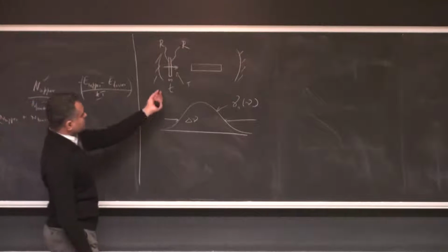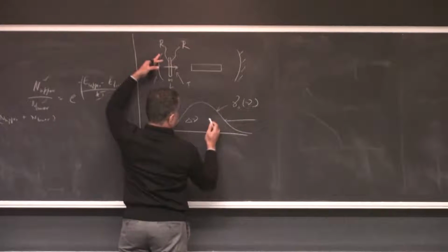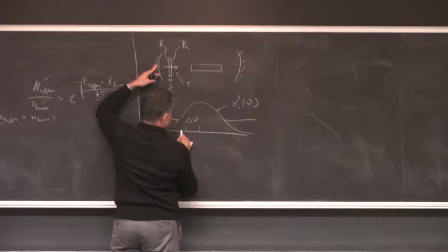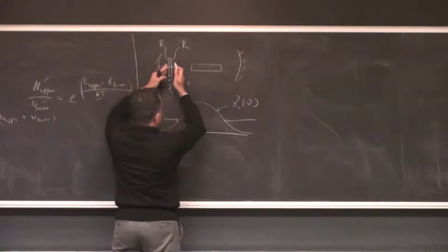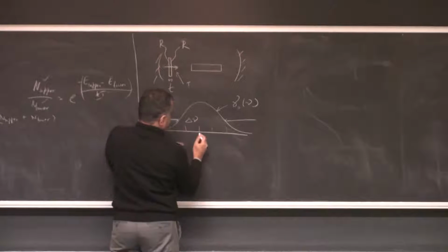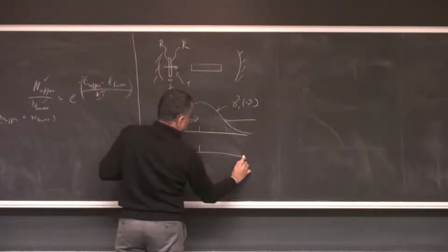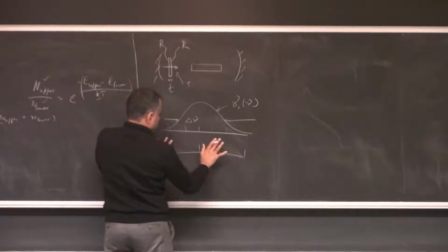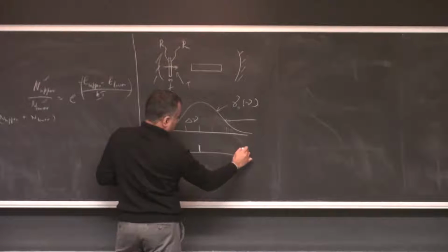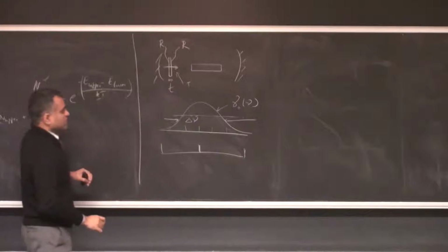The whole purpose of introducing this is that if your cavity size was this much initially and your FSR was closely spaced, meaning you had multiple modes, but if you introduce a much smaller cavity, you can have an FSR that is much more widely spaced, and you can push the allowed modes out into parts of the spectrum where you are below the gain threshold, and then you have loss.